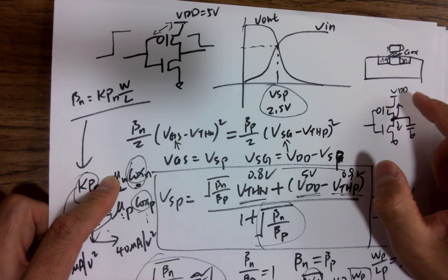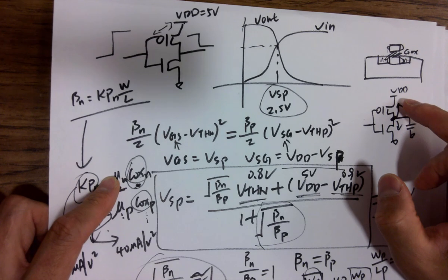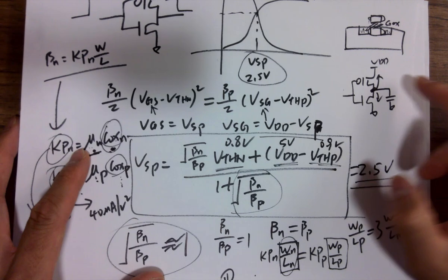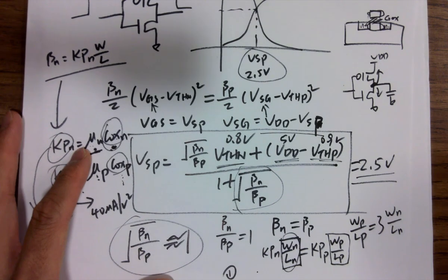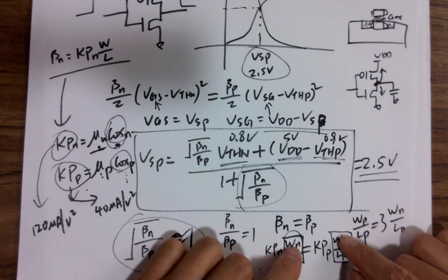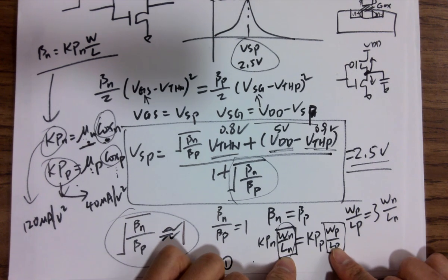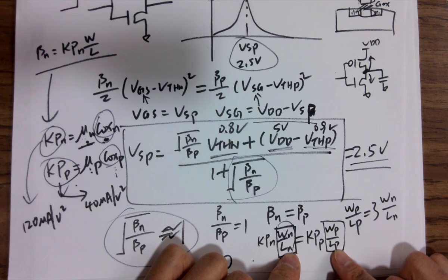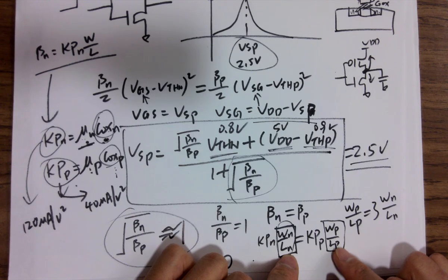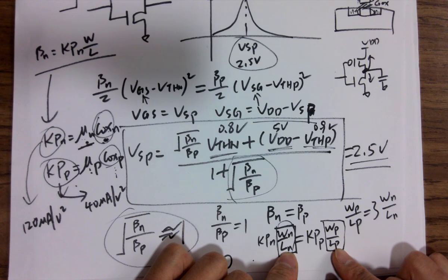So what can give you a stronger PMOS or NMOS? What determines the strength? Change the ratio. Yeah. So here's the ratio, right? Given that it's a certain type of technology we are using, if it's a TSMC 180 or C5, we know that we want to use the minimum length. We want to use the minimum required length without giving us any DRC errors. So in our C5, it's usually 2 lambda. 2 lambda will be what? 600 nanometers, because 1 lambda is 300 nanometers.